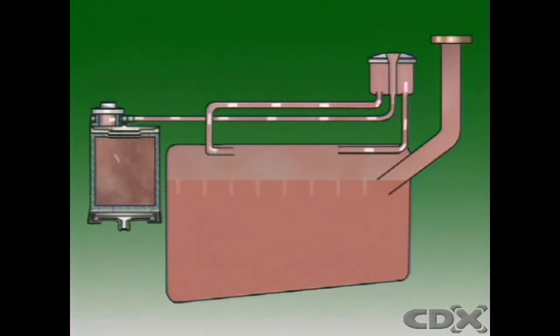This fuel tank has a small separator tank and a number of vents. They're from different parts of the tank, so that for as many vehicle positions as possible, at least one is always above the level of fuel in the tank.